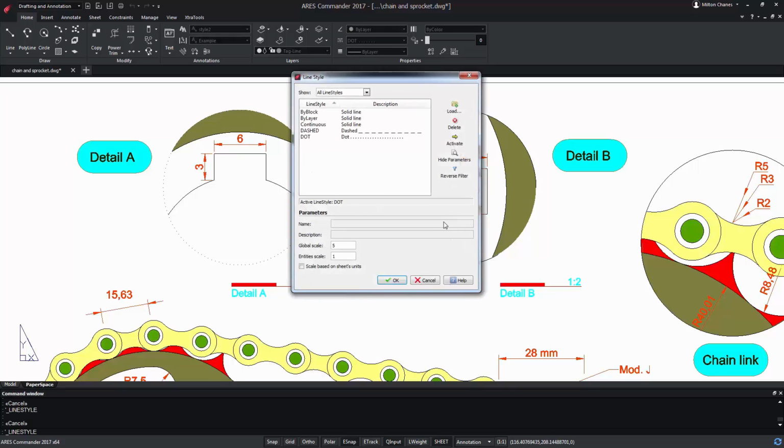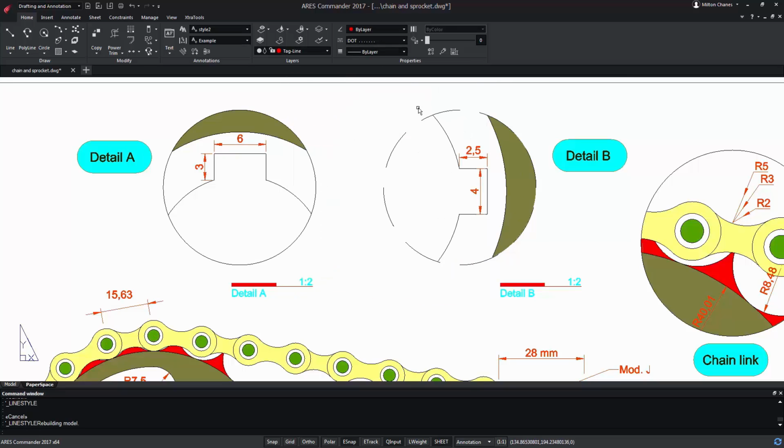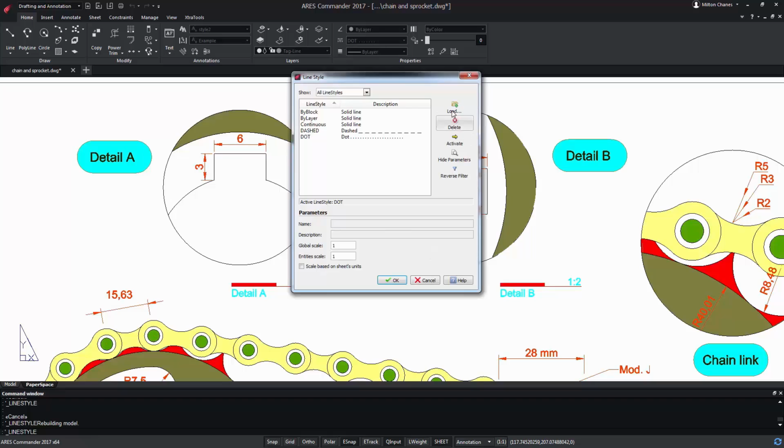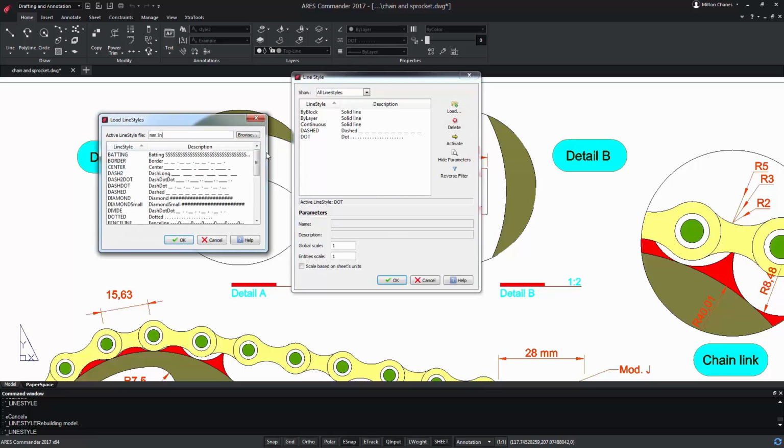This is where parameters such as global scale come in. You may, for example, change it to 1 to make the second line look better, although now the first one looks like a continuous line. In such a case, you could ask yourself if you are using the right set of line types, because in theory, the different line styles of a drawing should have compatible scales to avoid such issues. This explains why line styles definitions are grouped into a same file, and why you may end up customizing it.